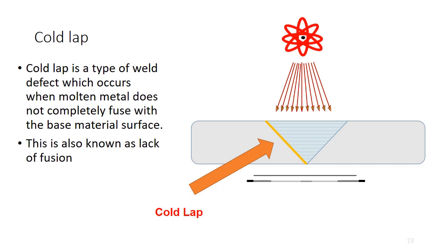So that's why, when you're going to do welder qualification, you can't use X-ray when you're qualifying your welders and you're doing the short circuiting mode, because they can put in a beautiful weld, but it doesn't tie into the base metal, and it'll just snap. Your bend test will just snap right on that fusion line, or you'll have a lot of cracks open up. So that's why they don't allow the use of radiography when you're doing welder qualification.